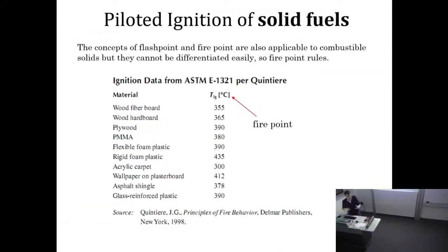We are very lucky that if you are interested in a specific polymer or material, you might have some information about it. The first thing, if you want to try to predict, to understand the time to ignition, is to know at which temperature, under standard conditions, this polymer will ignite. You have already seen this concept. It's the concept of fire point. It was developed for liquids.